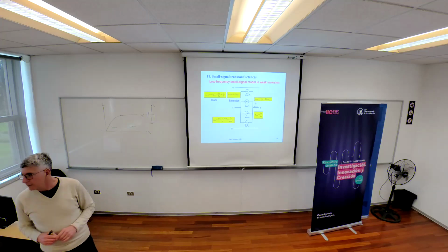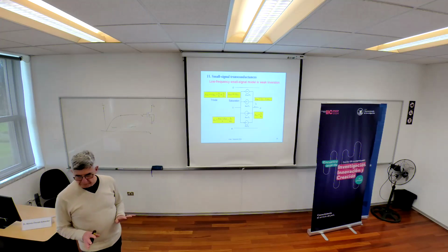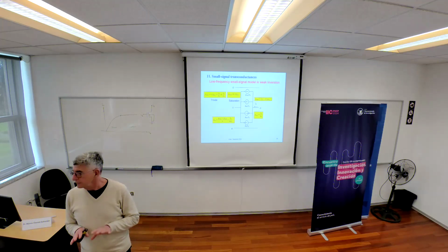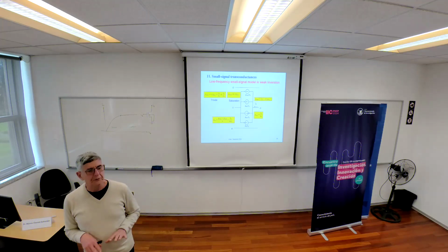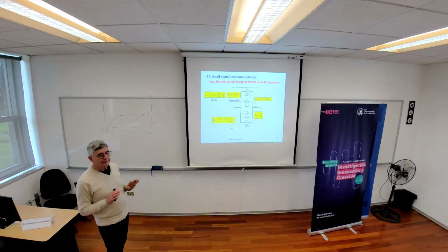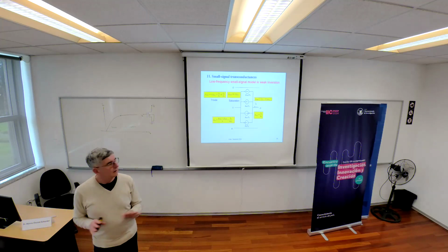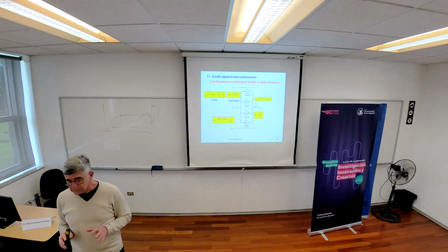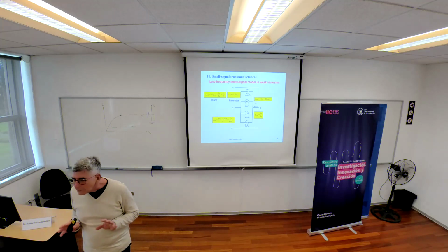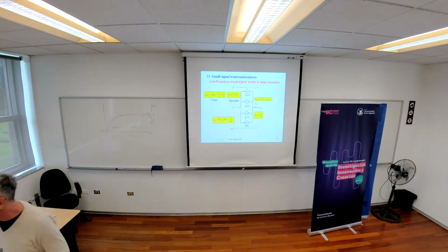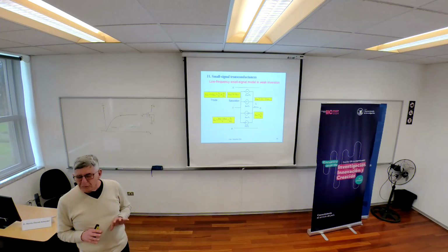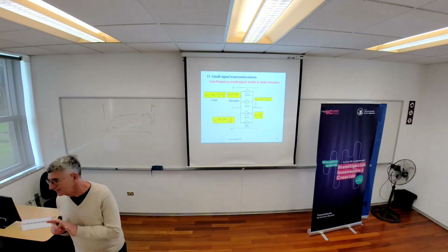In the final part of the class, I was talking about the transconductance of the AC model, or the small signal model, for very, very low frequencies. I'm not including the capacitances yet, but in one of the next slides, I will present the capacitive model, which is, say, quite complicated. But we circuit designers simplify this model a lot. We use just 5 capacitors instead of 16.